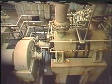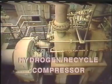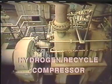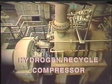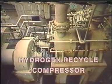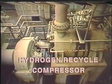Much of this hydrogen is recycled and mixed with fresh reactor feed. This is done to maintain a high concentration of hydrogen in the reactors. The amount of hydrogen in the reactors must be kept above a certain level, or the catalyst will be damaged.